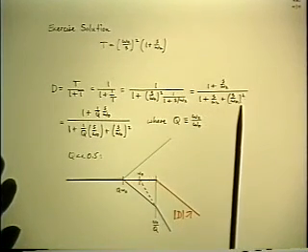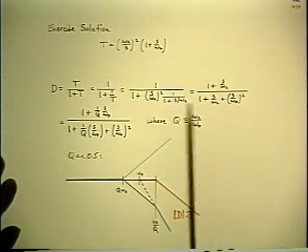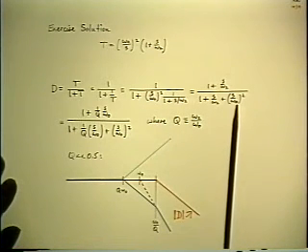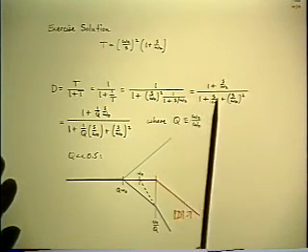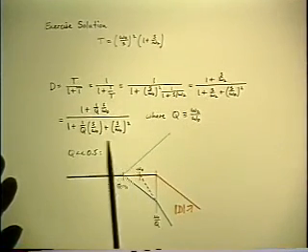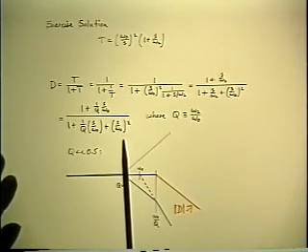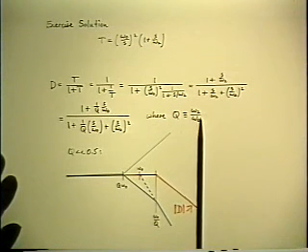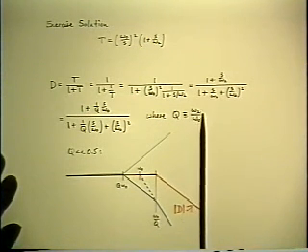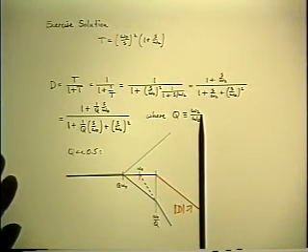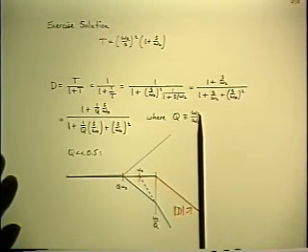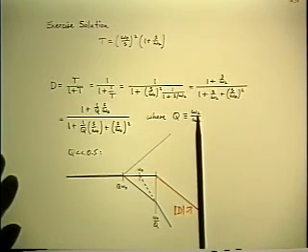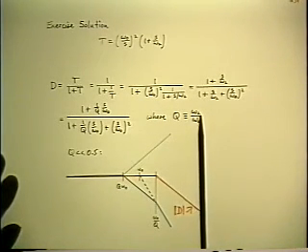And so you define a corner frequency, although as a matter of fact it's already defined, it's omega 0, and you define a Q factor in order to put the quadratic into the usual normalized form. And the Q factor is omega 2 over omega 0. Omega 0 is the fixed reference. Omega 2 is the position of your adjustable 0. And it can have any value, again, from 0 to infinity, depending on the position of the compensating 0.